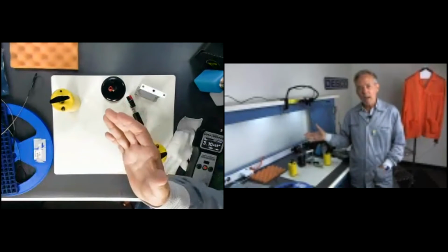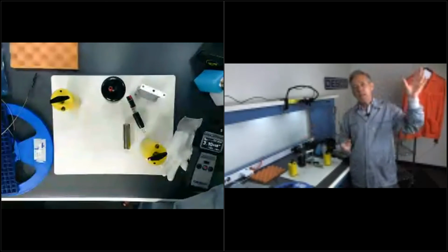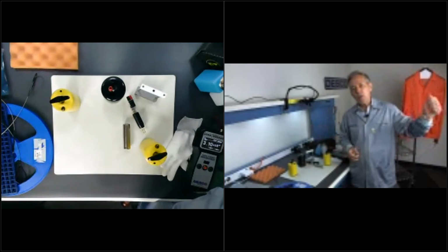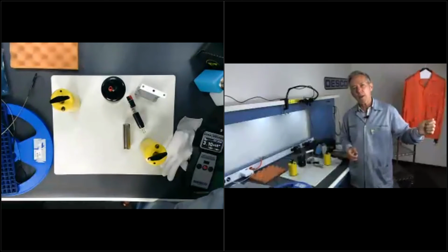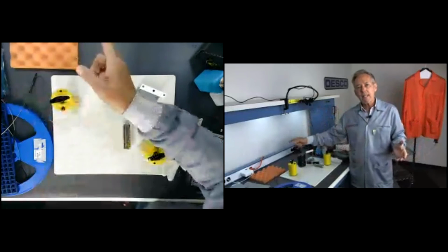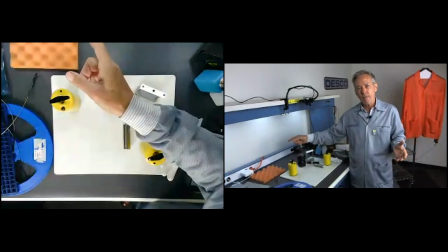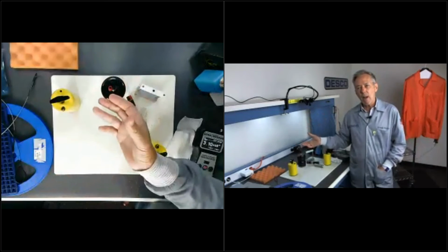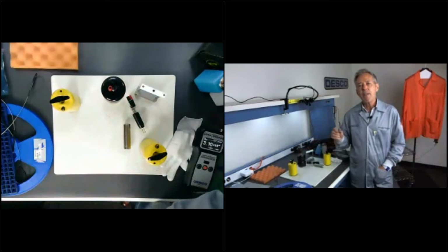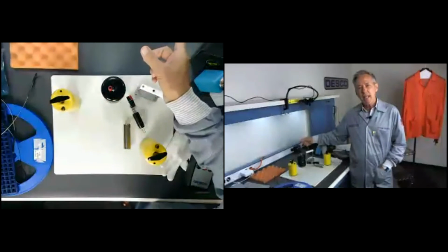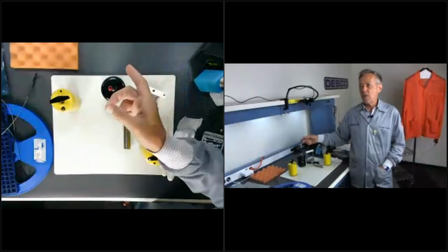One, it's already attached to the building services ground rod. Two, it's everywhere. And three, there's so much copper wire in a building of our size that even if the ground clamp fell off of our ground rod, I would still have a much lower potential that my static charge would bleed to. So both are acceptable, an individual ground rod or AC ground, but the standard does require that you now bond that individual ground rod back to your AC ground, and it needs to be less than 25 ohms.